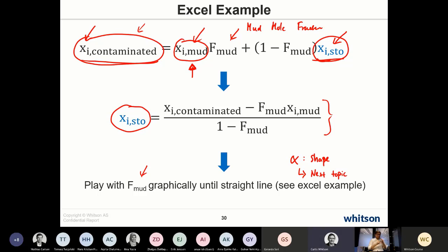The other thing on that, just a quick comment, Curtis, is that many places say that if the sample is contaminated more than 10%, for instance, then you need to throw out the PVT report. It's worthless. You can't use the data. Any comments on that?